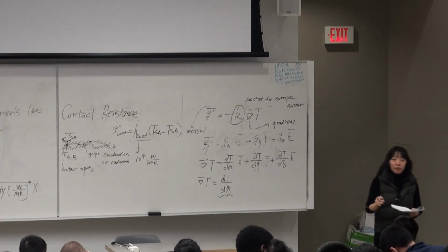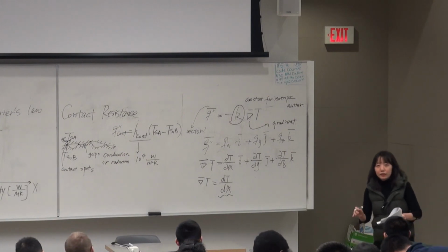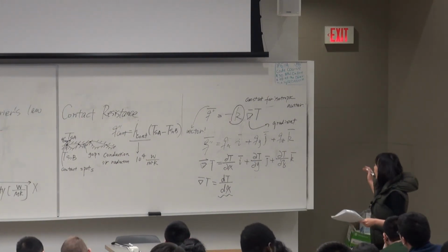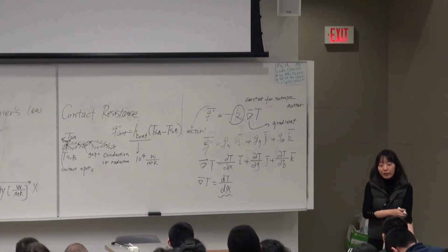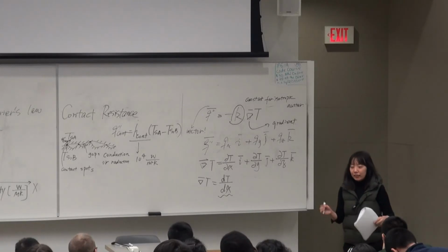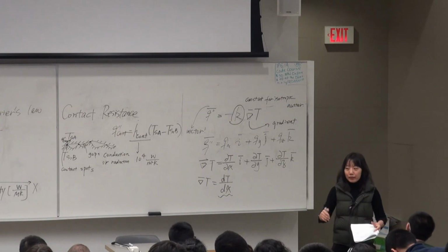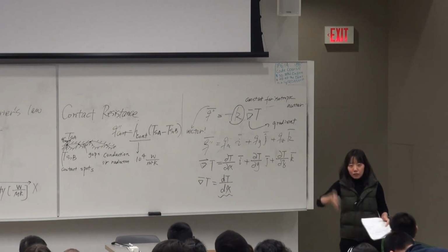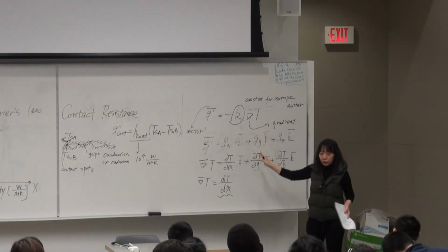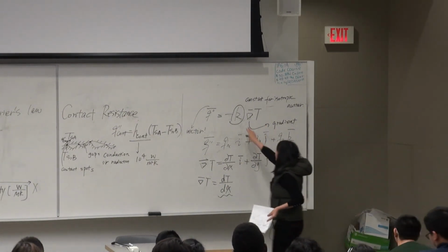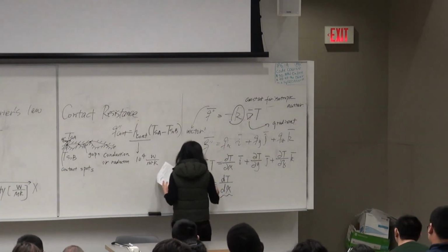Isotropic means the thermal properties are uniform in all directions. It's not a directionally dependent variable. But in reality, it's not always the case. For example, wood always conducts heat better along the grain direction than in the cross-sectional direction. So the more general way to represent Fourier's law, considering non-constant thermal conductivity, should be this.